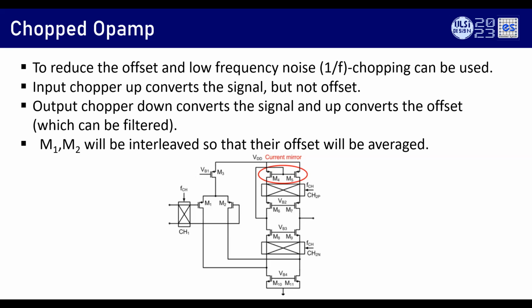If you do it at a high impedance node, you will not get it. If you do it at a low impedance node, you will get it. It will not get affected a lot. Yeah. So this has been explained nicely in the 2001 JSSC paper by Kofi Makinwa, explaining the nice thing about chopping, where to do it, why not to do this and all.